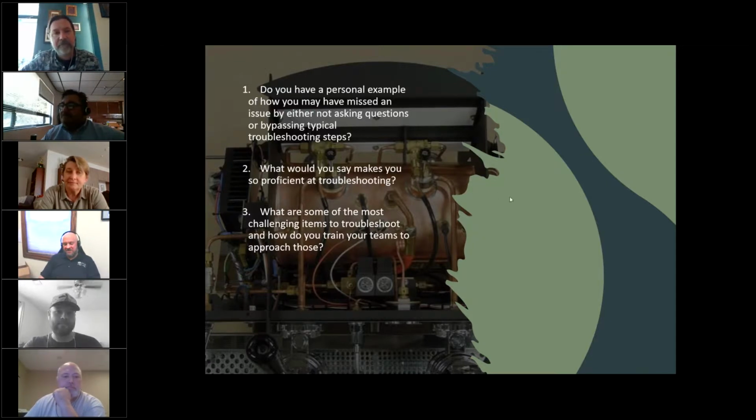Actually, I'll use one of my favorite things, NCV on the meter, non-contact voltage. And I've seen this and I'm guilty of it, where I was like, well, let me just hit something right there and see if I'm getting voltage to the part. Oh, I'm getting voltage. But I forget that on anything European, they're breaking the neutral or negative, whichever you want to call it, and so there's power to the part.